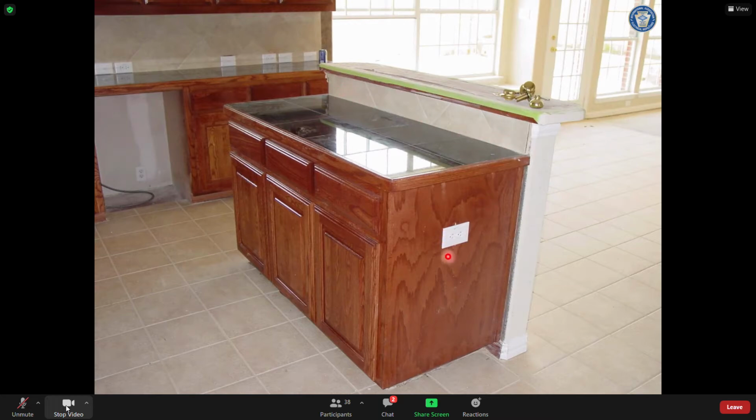Now on the rough end, when there was a piece of wire stuck up, rolled up out here, okay, I'm gonna have an island. But then when you get to the final, not only do you have a quote unquote island, that island has a backsplash. And so once that backsplash appeared, what else just kicked back in? The rule that you're no point any further than 24 inches from a receptacle just kicked back in. In other words, these are base countertops now. And so that's a code violation.